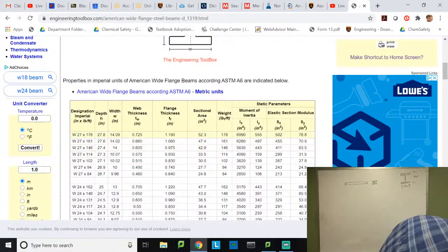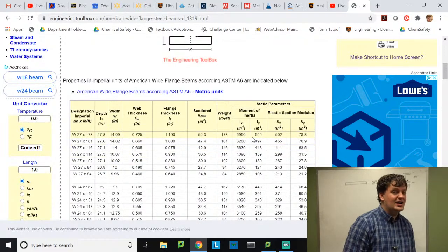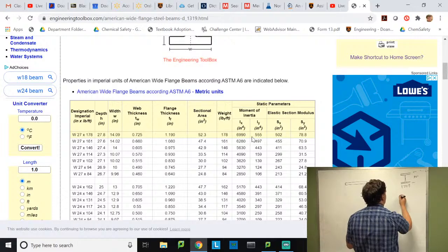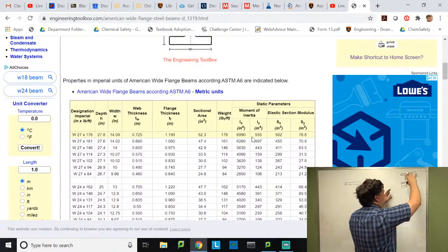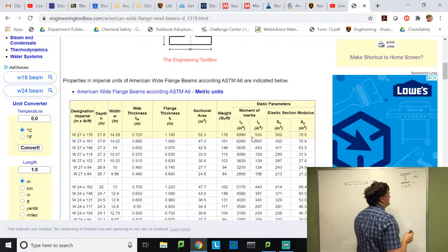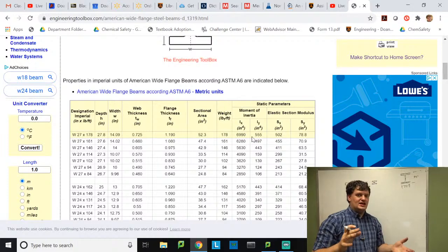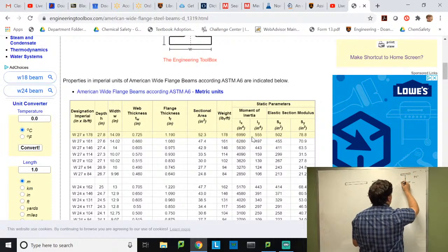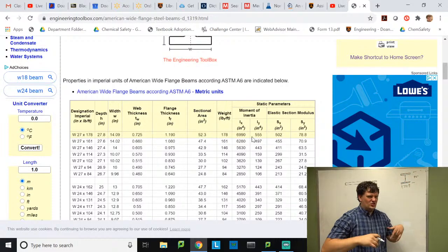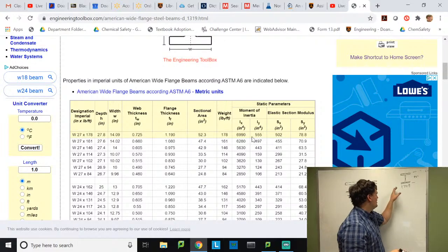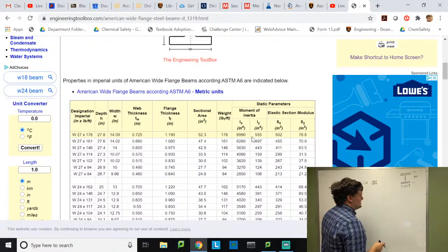You'll notice that the x directional moment of inertia is more than 10 times what the y moment of inertia is. It's the way that the beam is intended to handle. It's intended to flex so that the beam bends in this direction and it carries that bending stress on the top and the bottom here. If we were to turn this on its side and load it in the same way, it'd be carrying the maximum bending stresses at these 4 locations, and that's called the weak stress location for this beam. It's not as strong in bending that way. So yes, putting it straight up and down like this does give us an I-beam.